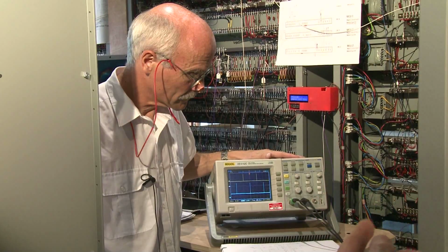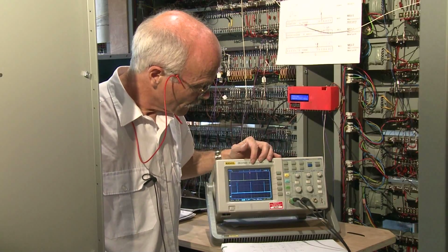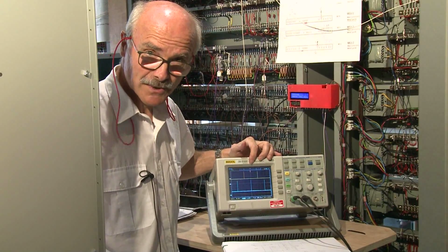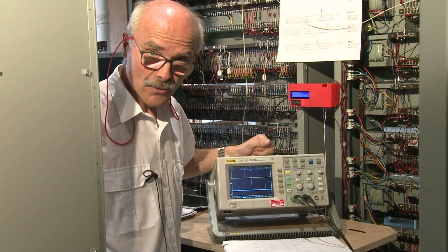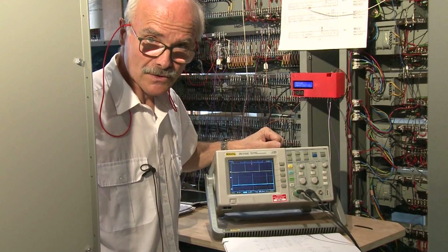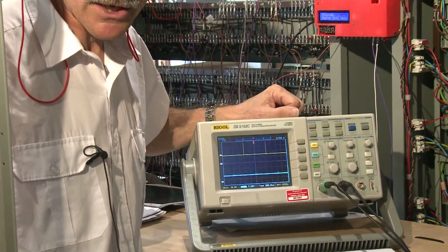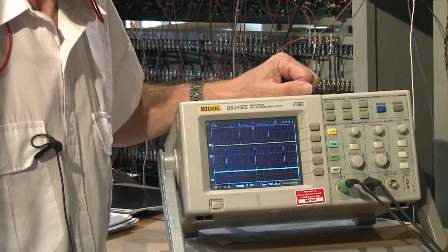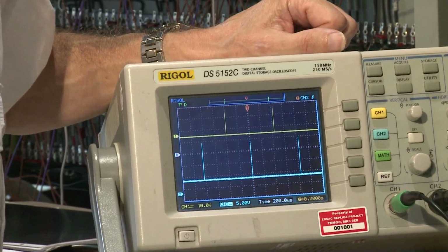So having got the R pulse, what does the master control unit do with that? The R pulse causes the commencement of the second stage of the cycle, which is to send out an S2 signal to the coincidence unit to fetch and decode the operand part of the instruction. Can we see the S2 being made? Yep.